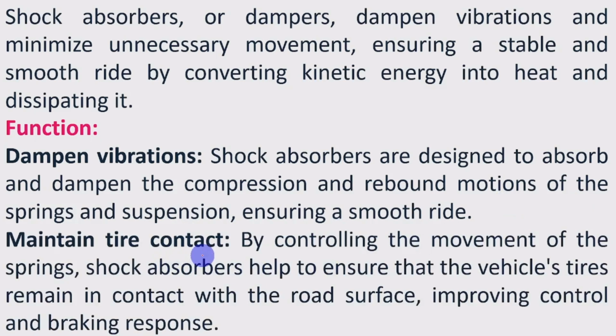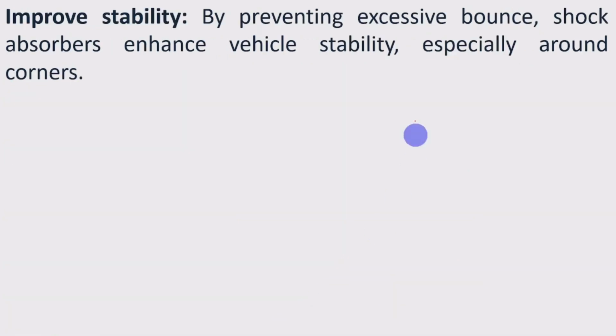Maintain tire contact by controlling the movement of the springs. Shock absorbers help to ensure that the vehicle tires remain in contact with the road surface, improving control and braking response. Improve stability. By preventing excessive bounce, shock absorbers enhance vehicle stability, especially around corners.